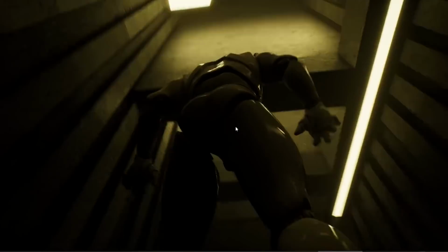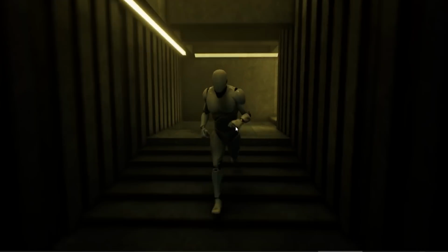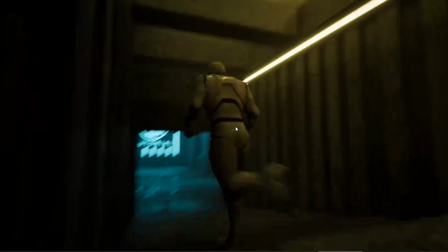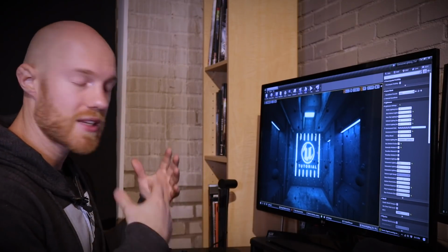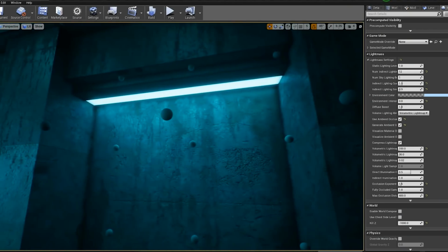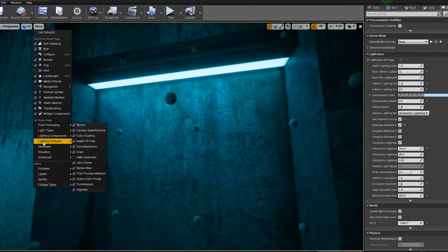And yeah, I have these little abstract light sources up in the ceiling here to get that kind of surrealist soft glow coming from above. But that's literally all of the lighting in my scene. So you can hopefully see just how quick and easy this is to really color your scene, add some really nice GI and soft lighting. Like I said, it works really well for strip lighting like this. You can see the falloff from the light. I'm just going to hide the volumetric light map for now.